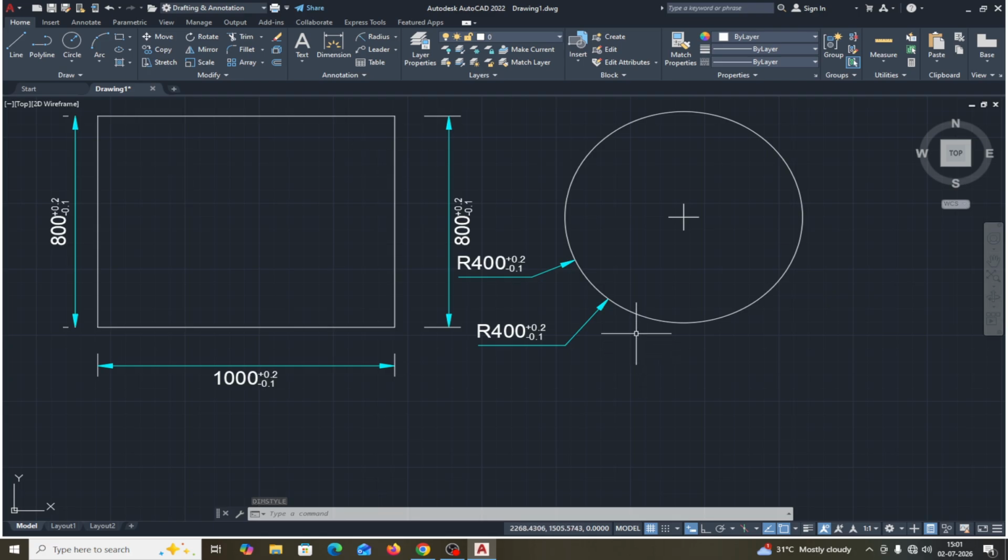In this way you can use the dimensions. Our purpose in the dimension style manager is to properly beautify the dimensional parameters, the different parameters. One is in the dimension, what parameters are there, the first is the dimension line, arrows, and this is the extension line gap. This is the gap between the text and the dimension line, and this represents the ISO representation mark. You can change it.